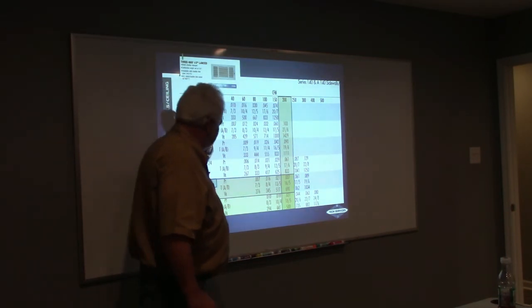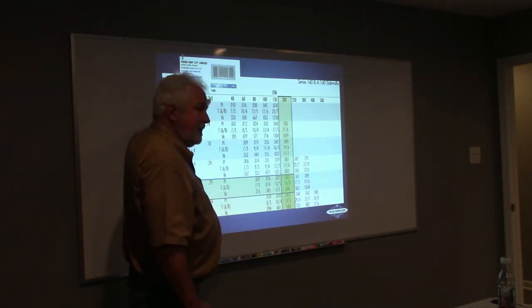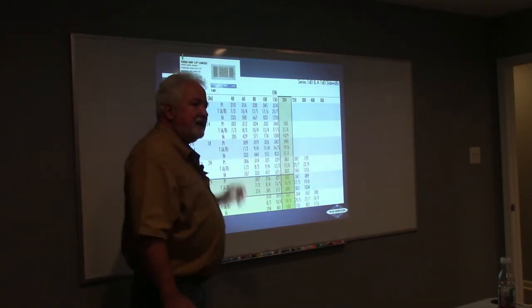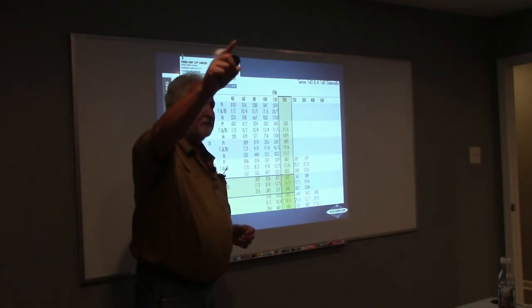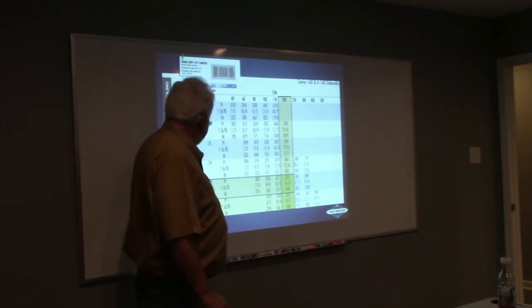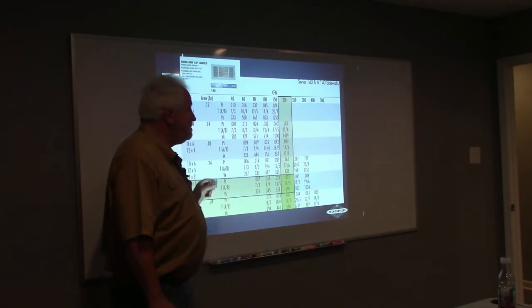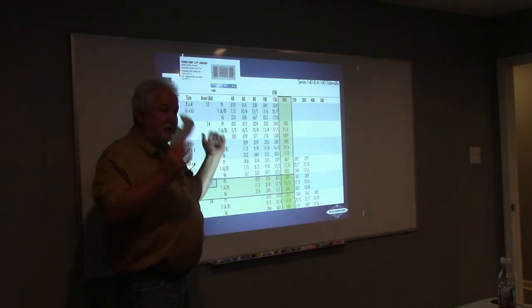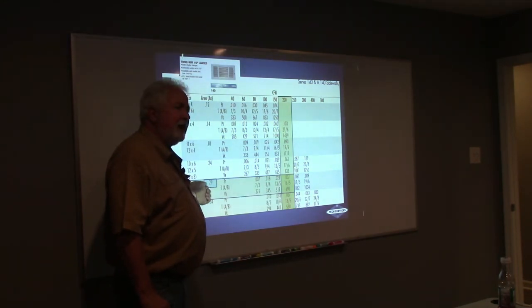Oh, I know what I wanted to do. I'm sorry. Back up here. See this area, AK? That AK is the free area of that grill. That's 12 by 12, so that's 1 square foot, right? But the AK tells me that of that 12 by 6 grill that we were just looking at, half of 1 square foot is 0.5, right?